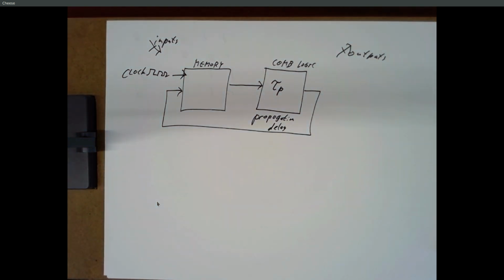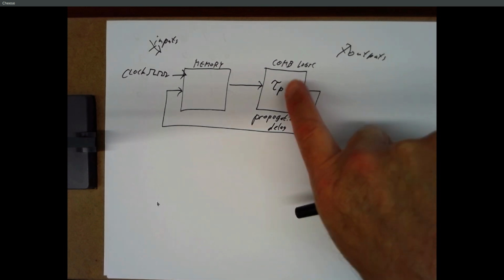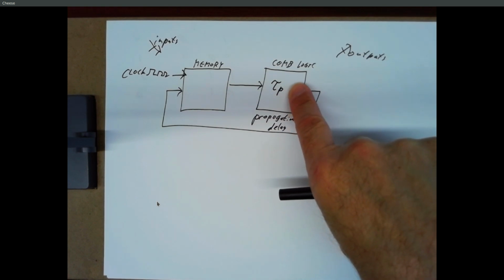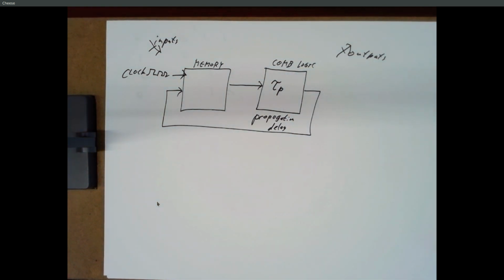Finding maximum propagation delay is tricky, especially if you have a million gates inside here. How do you figure out what the longest time is that it might take from changing one input to changing all of the outputs? You have to basically trace every possible path from every combination of input changes to every output, and then find the worst case. There's software that does this for us. But without that, you do this by hand. And you make some good guesses maybe, and then you throw in a little bit of padding, just to be safe. So there's a propagation delay associated with that.